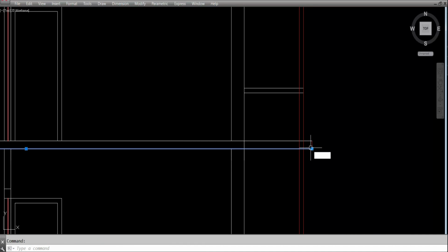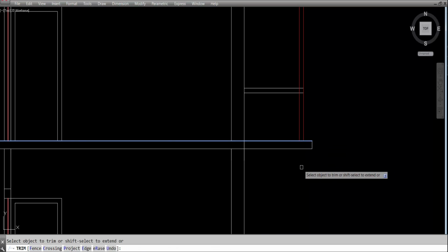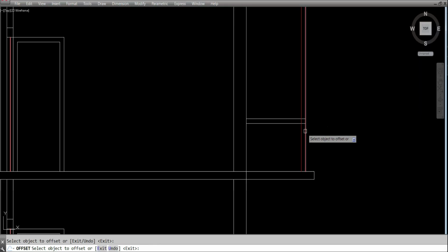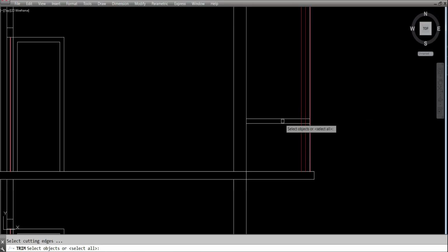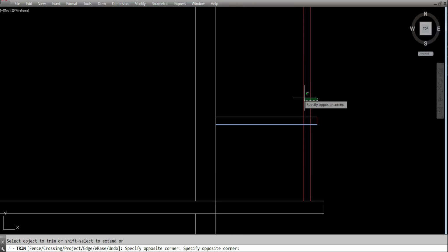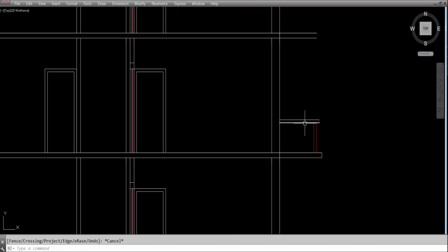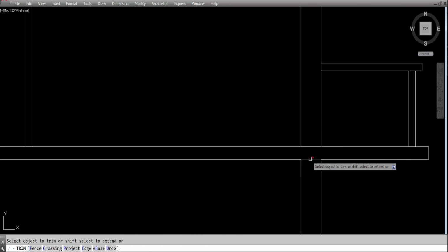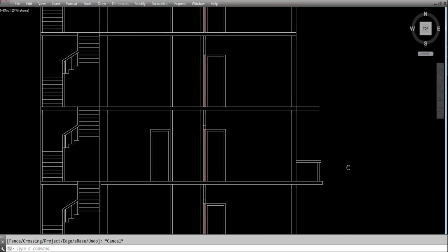Okay. I'm showing all step by step. Okay. Now trim. Select this. Also trim here. First give offset distance 3 inch to this side. Now extend this roof slab line and trim all this. Also trim from here. Okay, this is the balcony elevation, sectional elevation of this balcony with parapet wall. Okay, we can see the balcony, we cannot see. This is the parapet wall. We can see. All right, in elevation, sectional elevation.